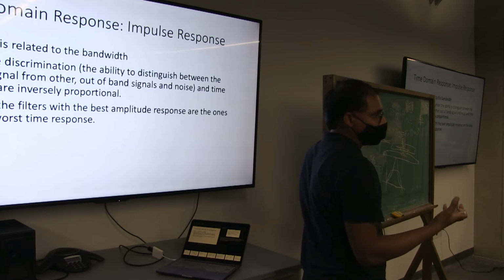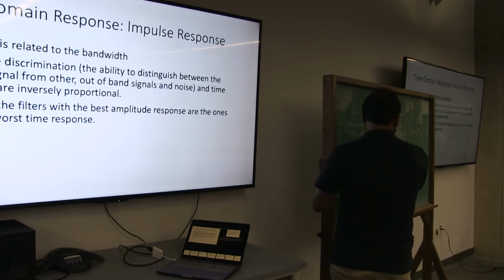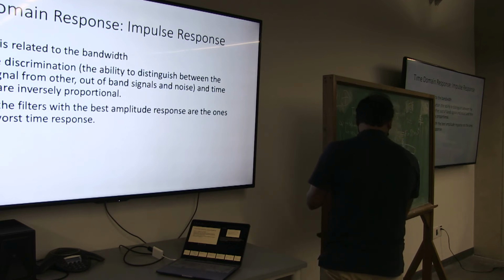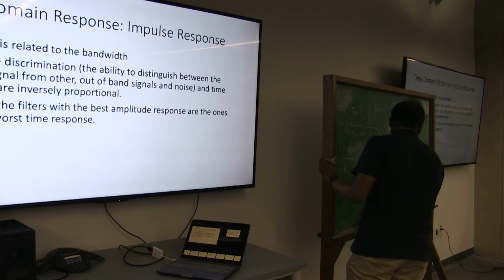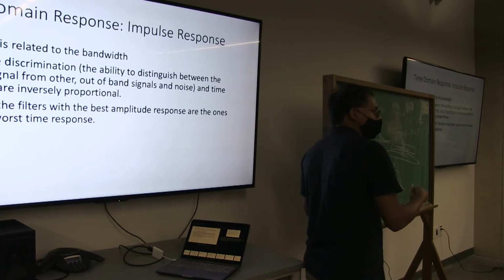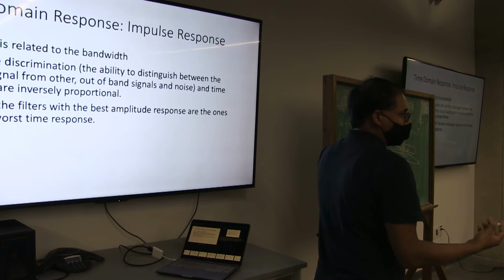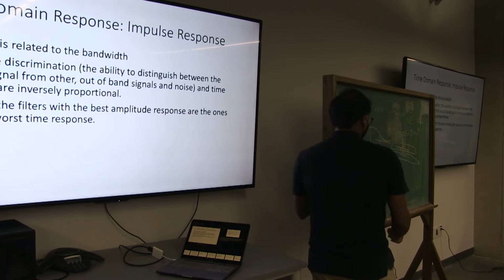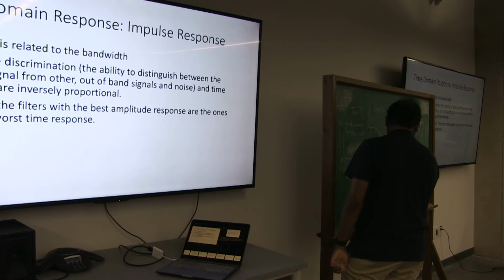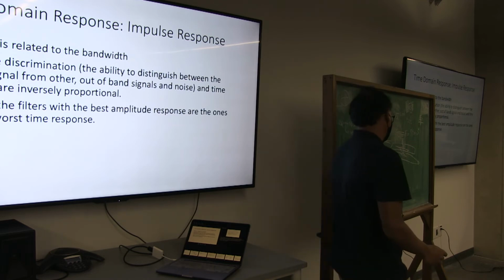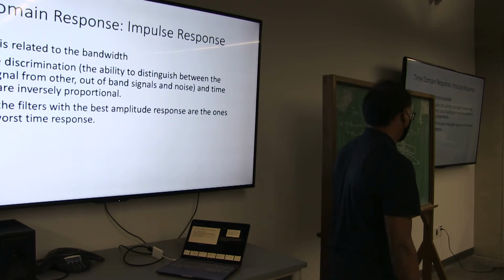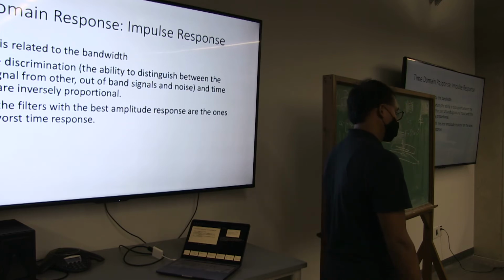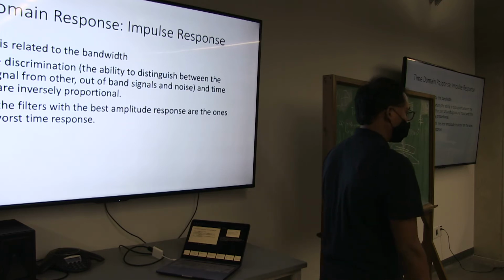So for example, if we are testing this in the lab, we have a filter that we design. We'll give a sine wave input and we'll check the output in a spectrum analyzer and see what is the change in the amplitude. For example, here we have a signal source. We are giving a sine wave at 1 volt at 1 megahertz, and at the output we got a sine wave of 0.9 volt at 1 megahertz. That means there is an attenuation of about 10%. So the filter corner is somewhere less than 1 megahertz, right?